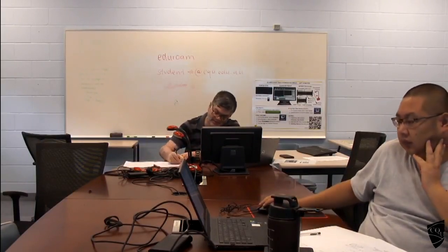So to find the deflection, I need the I value. But here the problem is, it is not simply a rectangle, it is a different shape. If it were a rectangle, it would be easy. So I need to find the I value about the neutral axis. For this rectangle, it is the center. So now we have a new neutral axis.